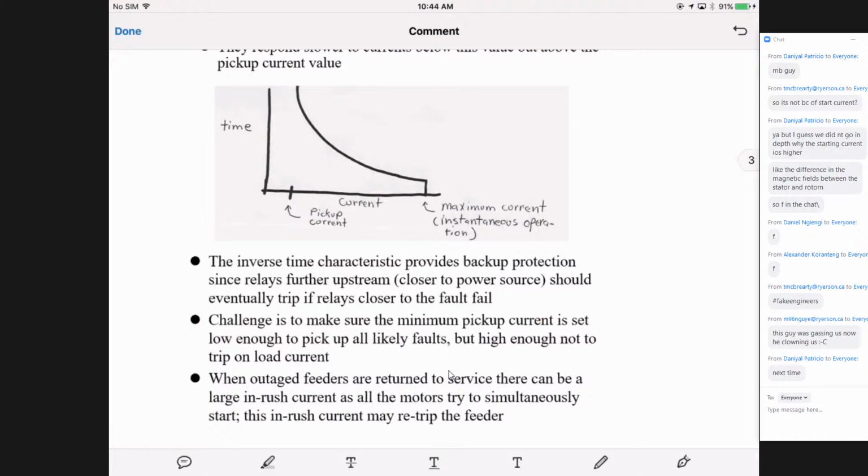Of course it's reasonable, because the inrush current is always there. If you cannot decide, then when you close the breaker, it trips again. When you close it, it trips again, and you don't want to close it a third time, because it may damage things. But you say, no, the textbook doesn't mention it. The textbook mentioned it in a sense, maybe not from one textbook, maybe not from one course, but it was mentioned.